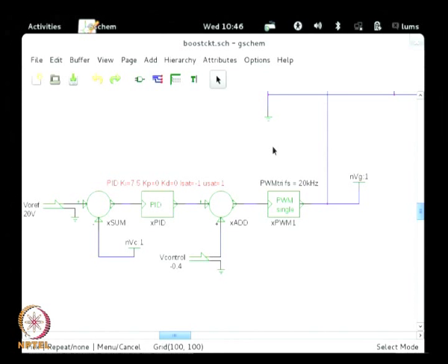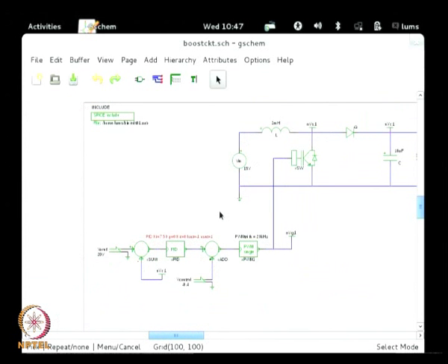So, this is basically the modification that I was suggesting we need to include, that is we need to have this feed forward term such that the controller is operating for only the small signal term, and in the steady state the D hat portion, the voltage corresponding to the D hat portion, will become 0. Okay.